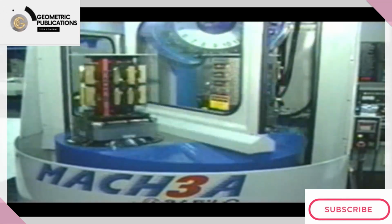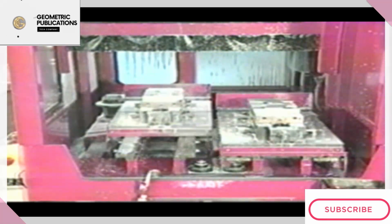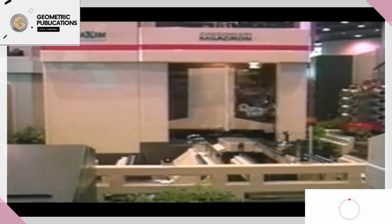The pallet changer swaps fixtures holding multiple parts from the setup area to the machining area. There, the second set of parts is machined, while parts on the first are removed and new parts set up.